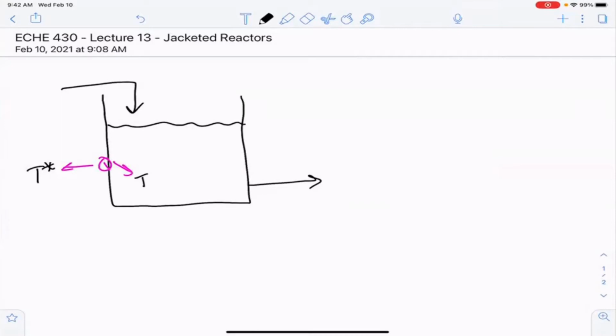We were able to tell them that they should look for a second configuration for the mash tun, which of course is where the barley is introduced to hot water. You remove the soluble starches, then the enzymes break those down into sugars, which you then ferment later. We suggested that they try to control the rate that heat is either lost or added to the reactor, or really maintain it at a known temperature, by jacketing the reactor. So this is another configuration that you could think of as well.